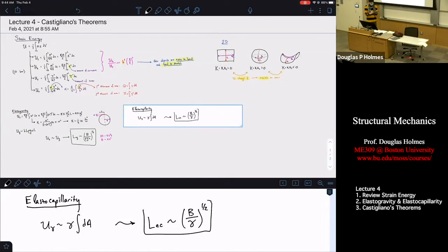What this length is telling you is when will a fluid cause fibers to bend. The simplest thing that I gave you in the paper was, imagine a cylinder of radius r, and imagine putting a flat sheet on top of it. And now just imagine that cylinder is wet with a fluid. The question that this is answering is, when will that surface tension be able to bend that sheet around that cylinder? You can imagine if that cylinder is incredibly small, it's going to take a lot of energy to wrap this sheet all around there. And if the surface is flat, it takes no energy to bend it on there. I mean, it's covering the surface without that.